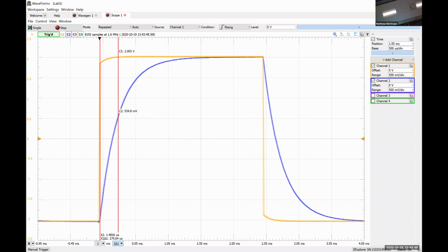We're adding the switch in. If we only did 0 plus, we would find that our equation would be discontinuous, and we know that can't be true for a capacitor voltage. Okay? So A represents y at 0 plus minus y at infinity. So y at 0 plus is what the value of the capacitor voltage is immediately after that leftmost red line. So what's that? And when I say immediately after, I mean literally a fraction of a second after.